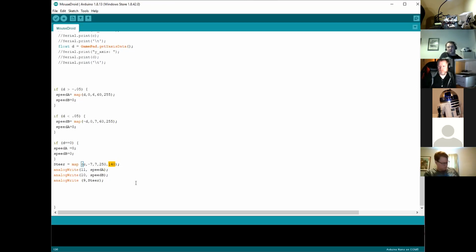Yeah. And just while we're still in this bit, going back to the Bluetooth connection. I see that you'd connected with a HC05. Is that correct? In that example that you flashed up earlier, where you connected the Bluetooth to the Nano. Yeah, the wiring diagram I got off Dabble's website, which did show a HC05. Am I correct that that's happy with Android, but Apple, or iOS, doesn't like that? That's my experience. Yeah, the HM10s support the BLE Bluetooth stack and the stack that works with the iPhone. So the HM10s I found are more compatible with both devices.